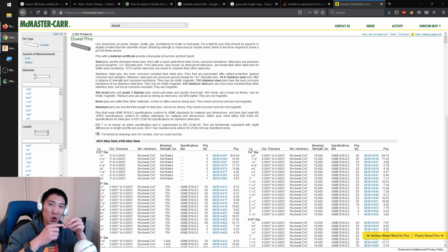It doesn't compress that far without damaging the collet. You can get third-party collets that will do like 3/16 of an inch or 1, 2, 3, whatever millimeters. But router collets don't have as much flexibility as an ER collet system, which you can get in 1/2 millimeter increments for every single size. So that is the one convenient thing about using an ER collet system.